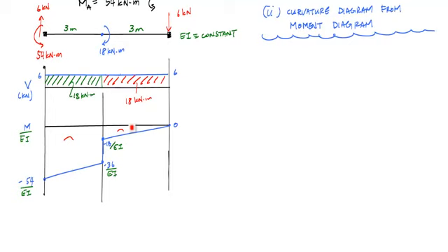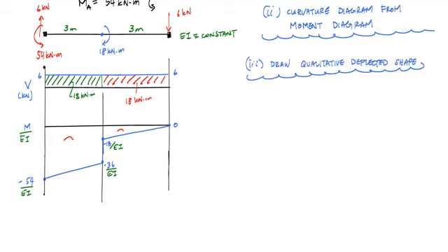And so if I obey the boundary conditions and I draw this deflected shape to match the way that a moment diagram is, I should get a sense of what the qualitative deflected shape looks like. Now drawing this qualitative deflected shape is not always easy, especially when the loading is complicated, and it takes a lot of practice, and you gotta see different types of structures and loadings over and over and over again until you get good at it.